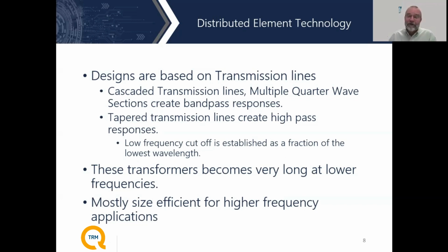So therefore, instead of having a high frequency of operation like we have in the lumped element technologies, we have a low frequency of operation, really that makes where these devices start becoming practical. And so that is one of the limits of going to a distributed technology, is that you have to deal with very long lines for very low frequencies.